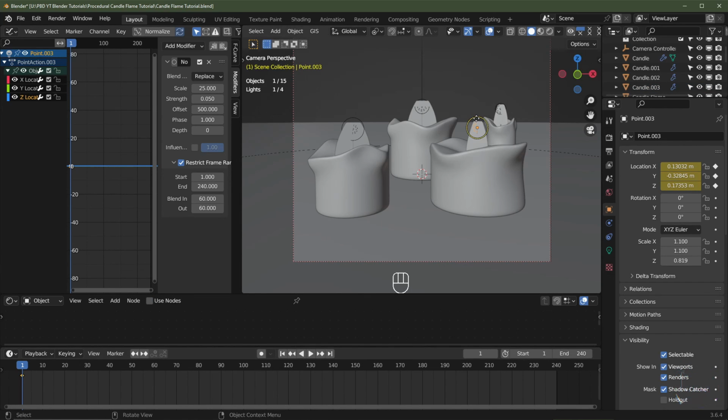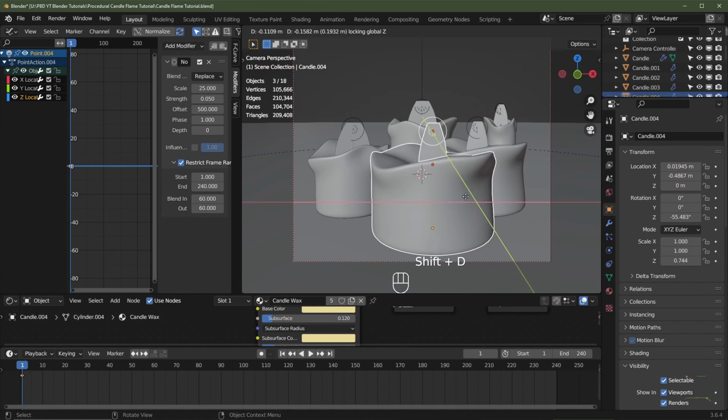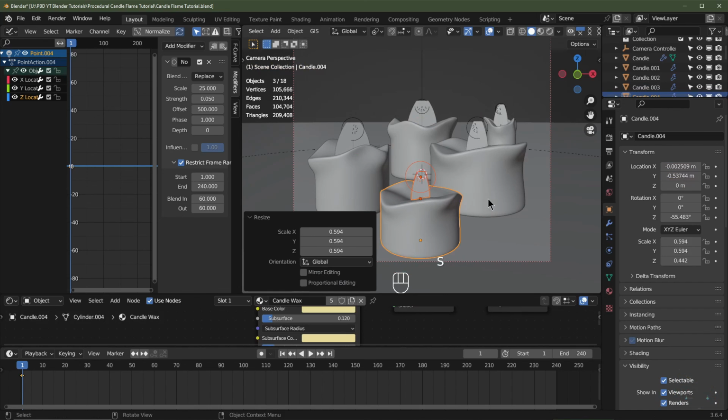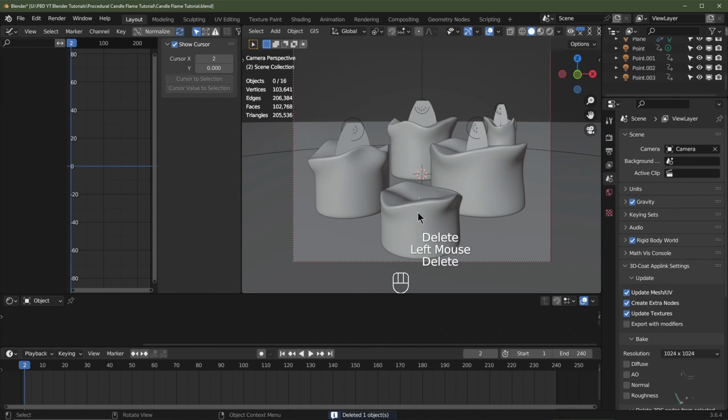And the reason why you want to add the locations is because, let me show you, I'll just select all these. I'm going to hit shift D, shift Z. I'll move this to here, for example. Now if I move a frame, this lamp here, which is 0.004, if I move it, it's going to go back to its original location. Okay, and we don't want that.